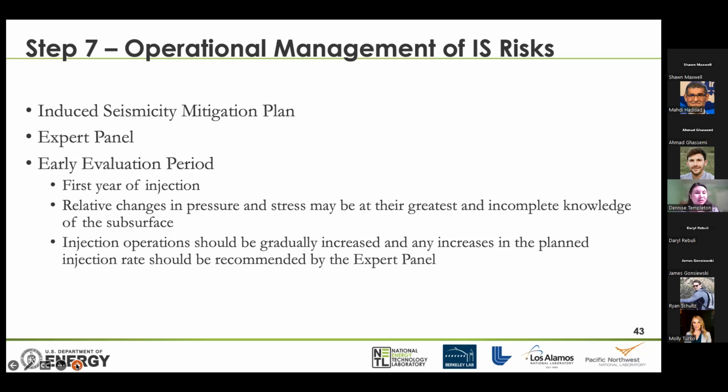We stress that there's going to be an early evaluation period. We suggest that's going to be about the first year of injection. The relative changes in pressure and stress are going to be at their greatest. And we also know that we're going to have an incomplete knowledge of the subsurface. And so how can we proactively decide what we need to do during this early evaluation period? We discussed how injection operations should be gradually increased, and that any increases in the planned injection rate should be recommended by the expert panel.